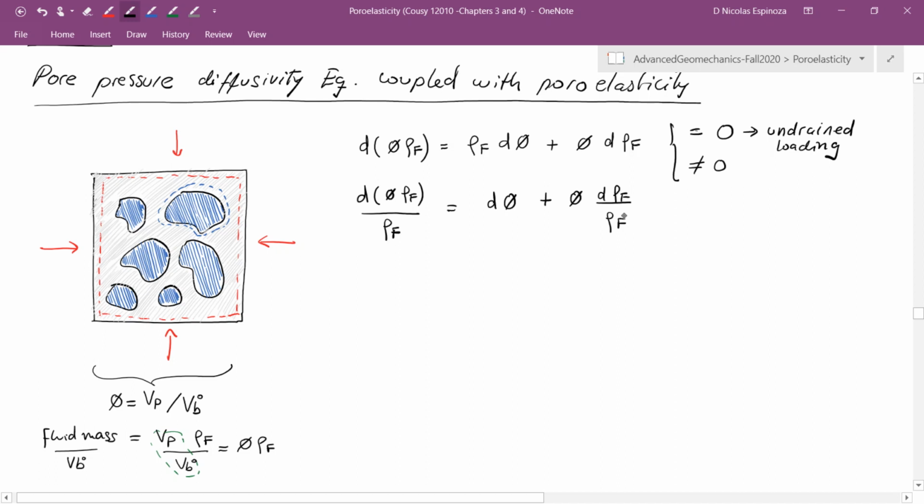All right, so from here, there are two things I can do. First, I hope that you remember that from the third equation of poroelasticity, we could calculate the changes of porosity. And these changes of porosity, according to the theory of poroelasticity, are related to this equation, which depends on the Biot coefficient, the volumetric strain, the pressure, and the pore modulus.